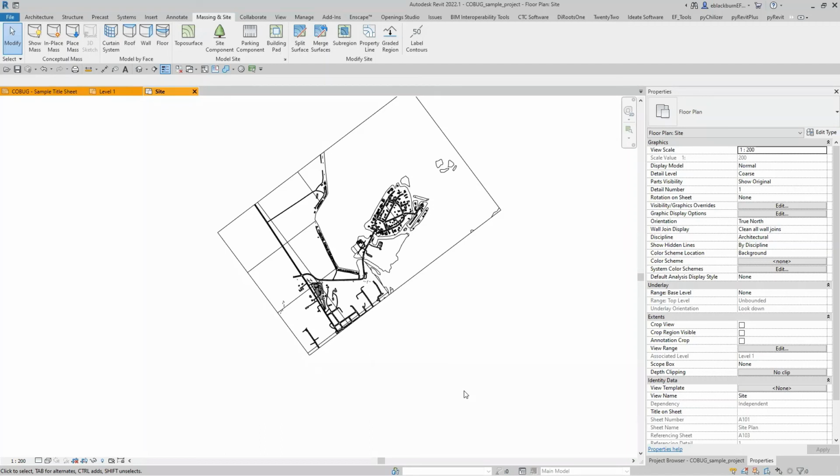The other thing that's really nice in 2023 Revit is the fact that your site boundaries now can actually follow and have both concave or convex edges, essentially. It used to be the case where if your site had a concave edge, it would kind of span across those and give you extra surface that you didn't want. In the new version of 23, it actually will follow those boundaries better and lead to less overlap, and a lot more control on how that works.